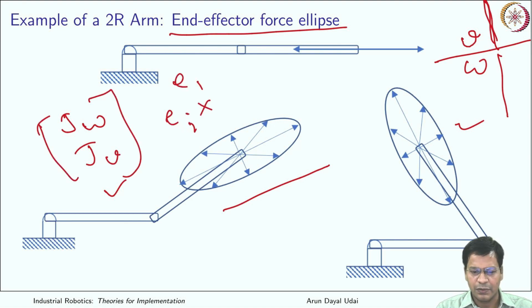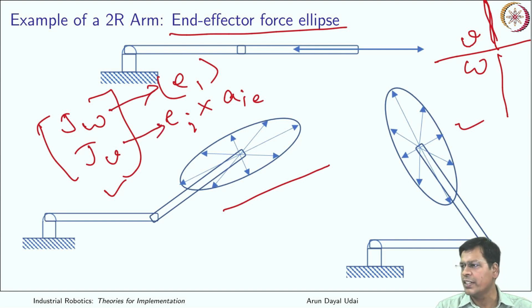So this part was taking care of the angular velocity component, and this part was taking care of the linear velocity component. So even for a 6 degrees of freedom robot, you get to see the angular velocity ellipsoid and the linear velocity ellipsoid. Okay, so that is the case if it is a 6-DOF robot. At least for 6-DOF it is quite trivial and almost easy to understand, but if it goes very high, it becomes a hyperspace. In that case it is difficult to visualize it geometrically, but the idea remains the same.